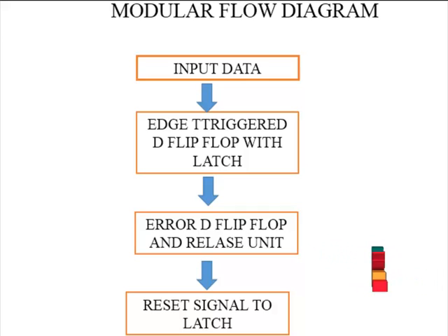A logic 0 on the asynchronous input S at any time will cause Q to be set to logic 1, from the time S goes low until the first clock pulse after S returns to logic 1. A logic 0 on the asynchronous input R will cause Q to be reset to logic 0, from the time R goes low until the first clock pulse after R returns to logic 1. The action of the asynchronous input overrides any effect of the D input. Both asynchronous inputs should not be low at the same time, as both Q and Q bar will be at logic 1. This is a non-allowed state.